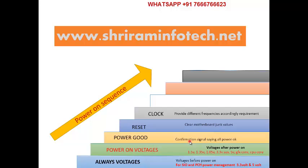If the PCH clock does not come, do you replace the PCH? First you have to check the 25 megahertz crystal. It is not necessary to replace it with a new one. A new PCH? Yes, you have to replace with a new PCH only. First try to heat.